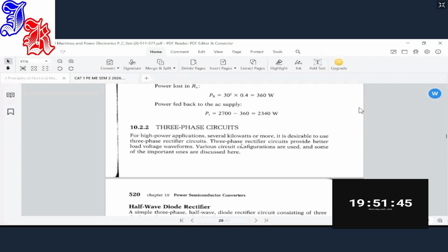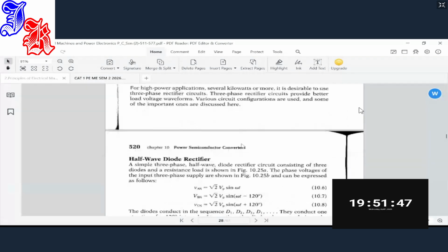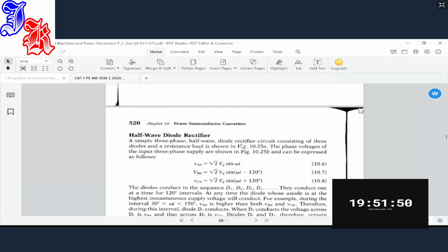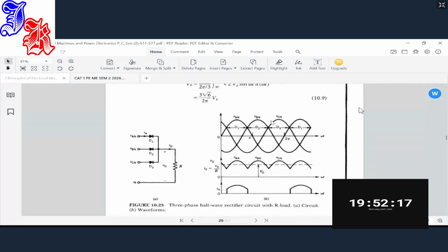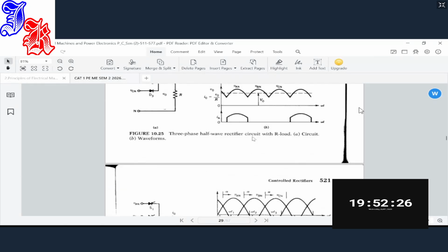The moment you understand the single phase system, the three-phase system is easy because it is more of these single phases put together, three of them, but they do not start at the same time. We normally say they are electrically displaced by 120 degrees. So if the first one is at 0 degrees, the other one will be after 120 degrees, and the other one before at negative 120 degrees. So we have this one, this other one, and this one to make a three phase. But for this unit we will not be covering those.